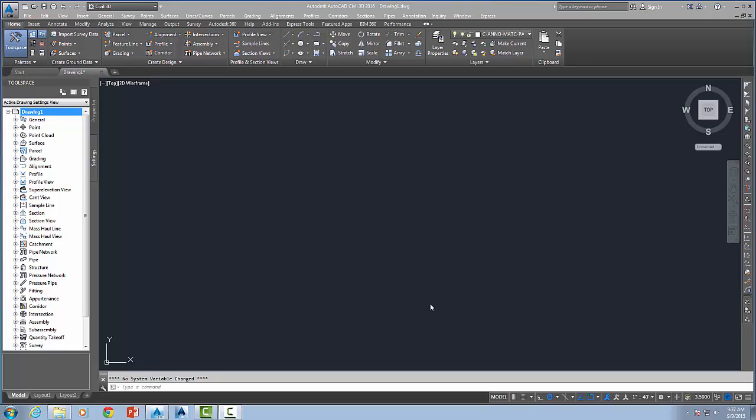Also, once we get our control in, you notice we've got a little traverse, 1 through 6, and we're going to be locating points off of that using a combination of angles and distances, different types of angles. So we'll be thinking about that. We're going to introduce the point object today and get you used to it, and then we'll be building on that in the next lab as we get into the route location types of things that we're majorly looking to do.